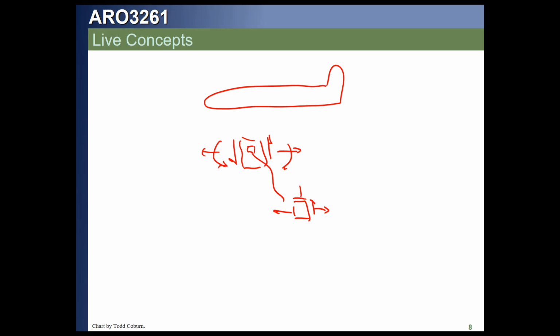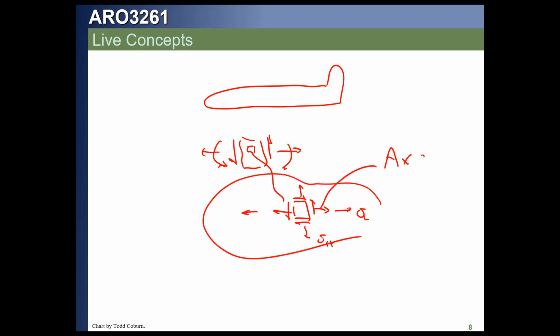Because we have internal pressure, we will also get a longitudinal component of stress and a hoop component of stress. So the total stress state will include the axial load and bending components and the pressure components. Generally, our inertial loads will just cause loading in plane.